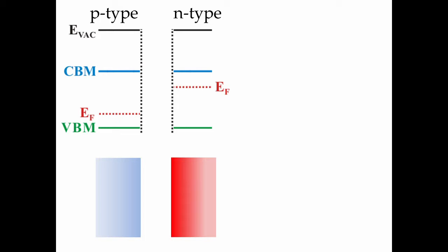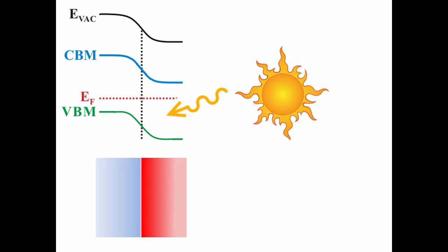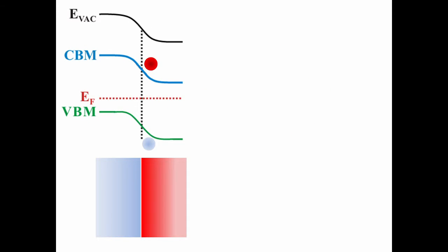The design of the solar cells we fabricate are based on the common diode and include either a PN junction, shown here, or a PIN junction, in which two materials are brought together with very different electronic properties to induce an internal electric field. When these materials absorb light, they're able to separate out optically excited electron hole pairs and produce currents that move in opposite direction throughout the materials.